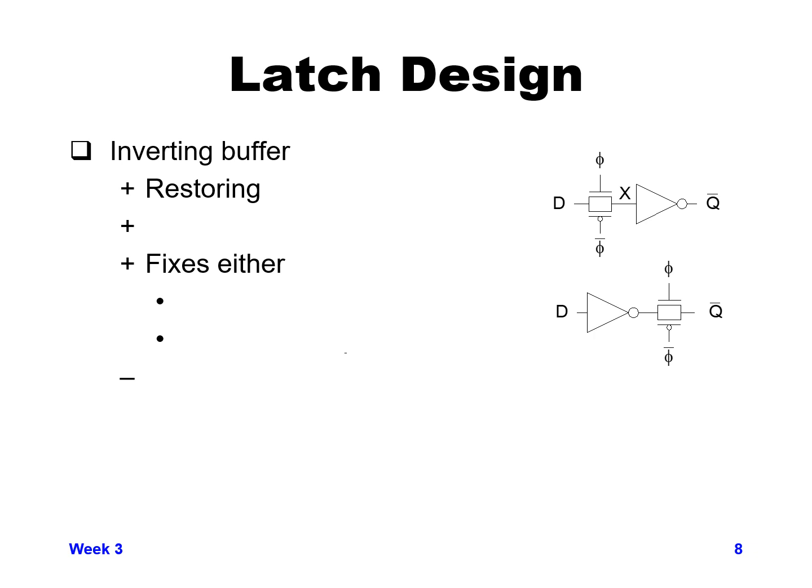If a value comes into the data input that isn't quite a 0 or 1, our output will get restored, inverted, but restored to a full 0 or 1, and we don't get any backdriving. So one con that is removed is backdriving, because we have that buffer in there.